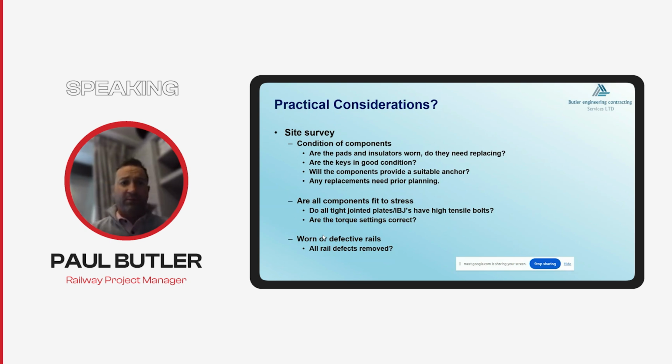So, condition of components. Are your pads and insulators worn? Will they be fit to stress against? When you clip everything back up, will they actually hold the stress? Are your keys in good condition? And this isn't all about the toe load, whether it can hold stress. It's whether you can actually get them out or not. The amount of times we've been to sites where, in our preparation work, you can't get the keys out because they've seized, because they may have sat in inclement weather for many years. So you need to consider whether you need to do any component replacement prior to doing the stressing.